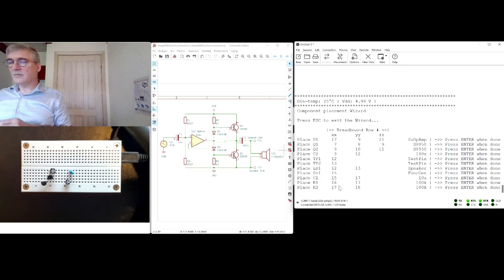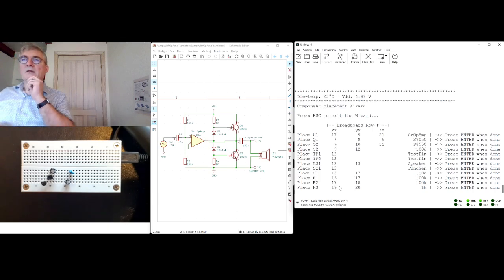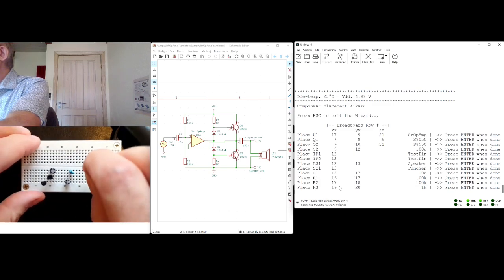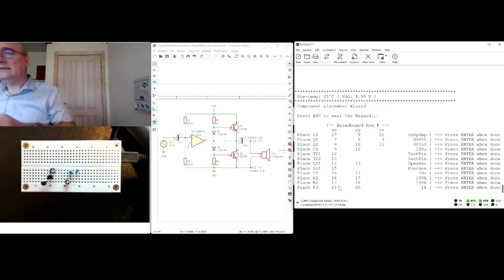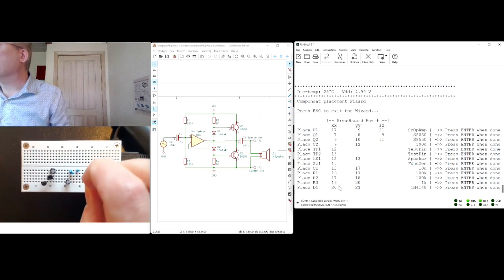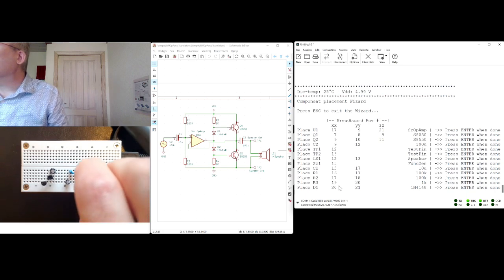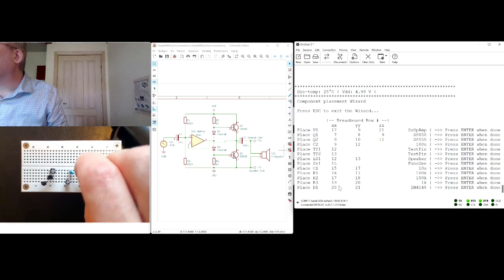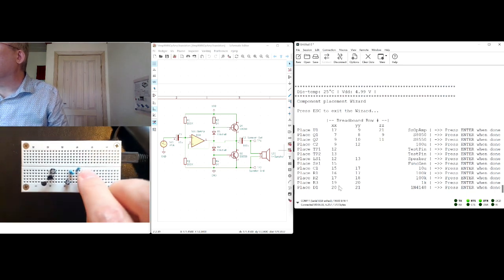That is then placed. We'll take the next one, 19 to 20, a resistor, and I'll put it into 19, that's here, to 20. The next one is the diode, and I'll take the diode and place it. Of course, if it's misplaced, turned in the opposite direction, the system will tell you that you need to turn this diode, so you have the anode and cathode the right way.